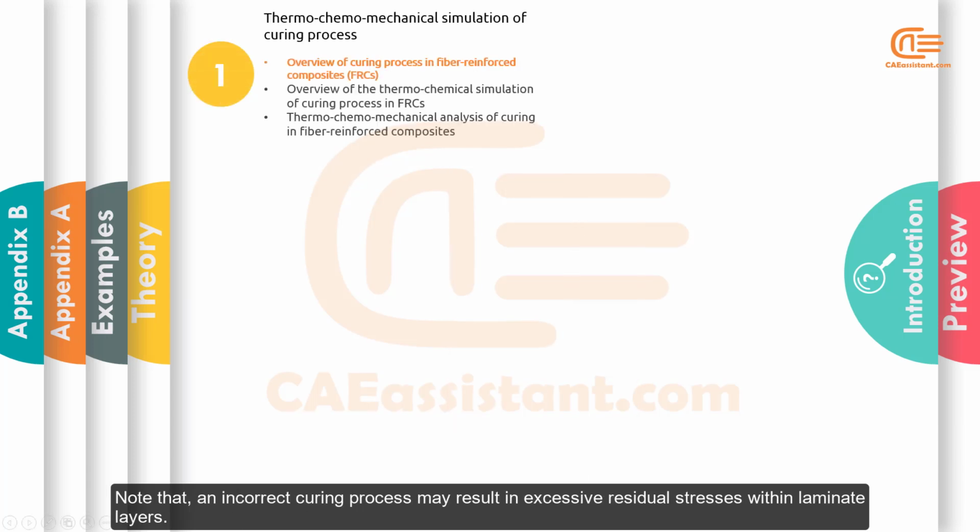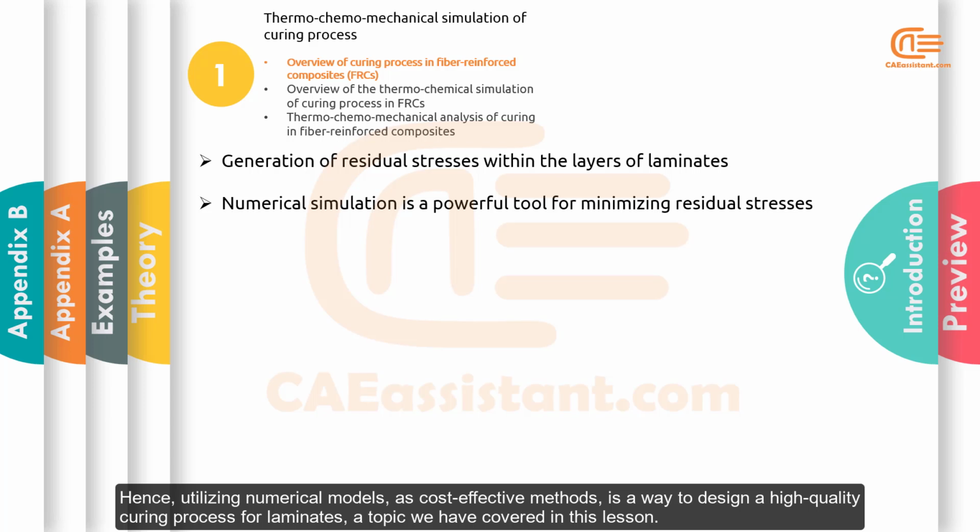Note that an incorrect curing process may result in excessive residual stresses within laminate layers. Hence, utilizing numerical models as cost-effective methods is a way to design a high-quality curing process for laminates, a topic we have covered in this lesson.